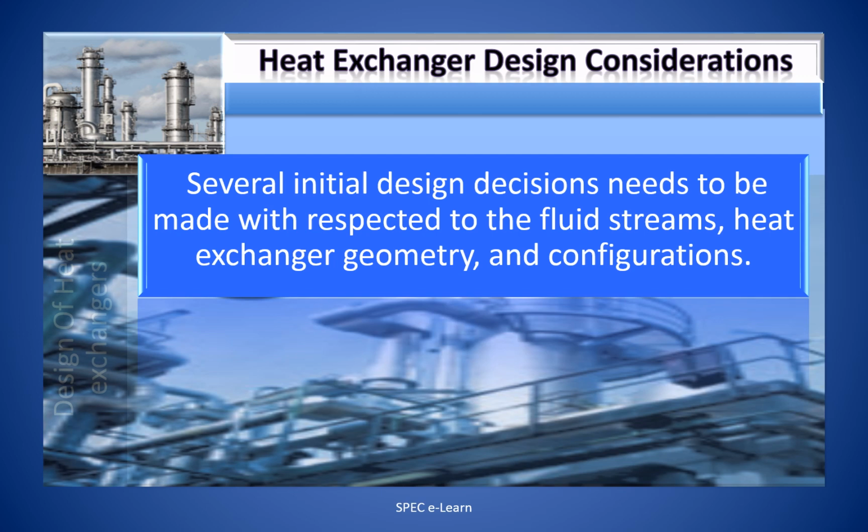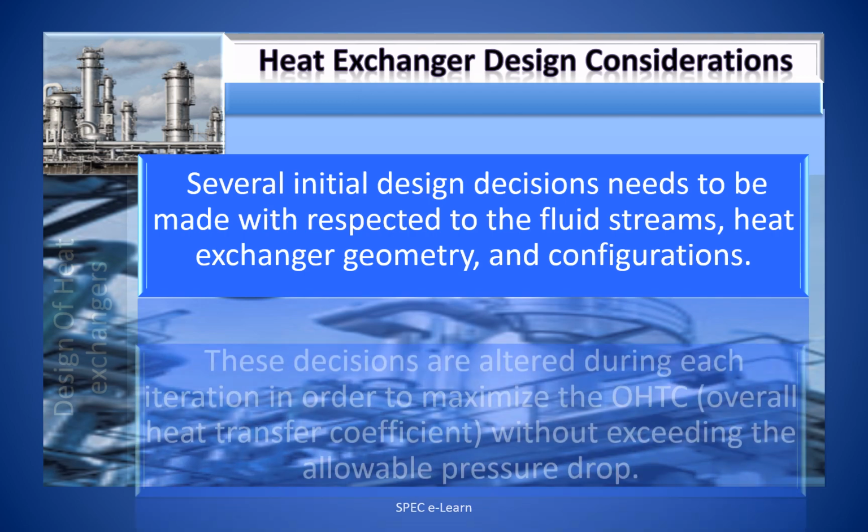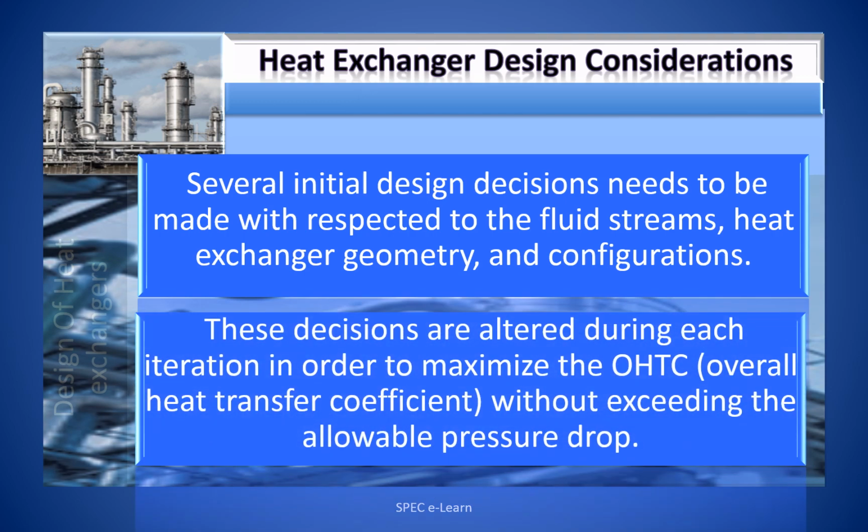Several initial design decisions need to be made with respect to the fluid streams, heat exchange geometry and configurations. These decisions are altered during each iteration in order to maximize the overall heat transfer coefficient without exceeding the allowable pressure drop.